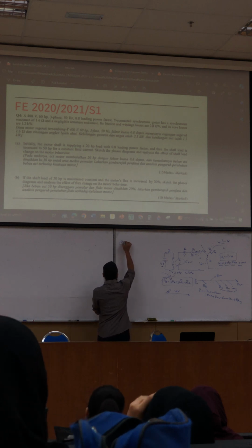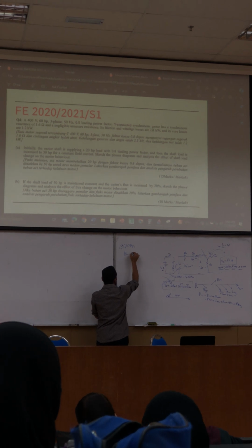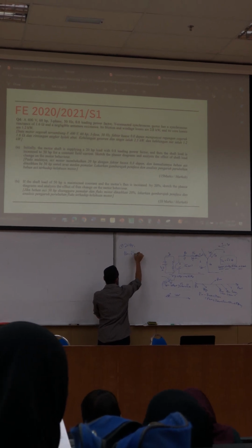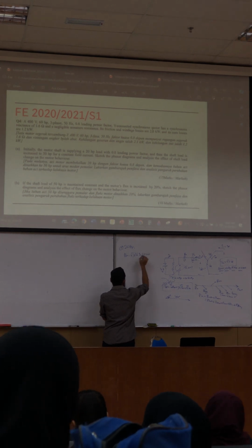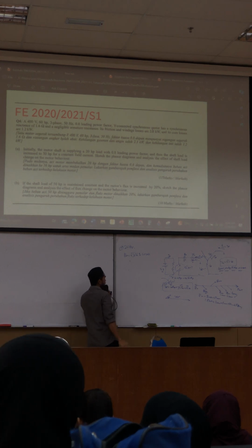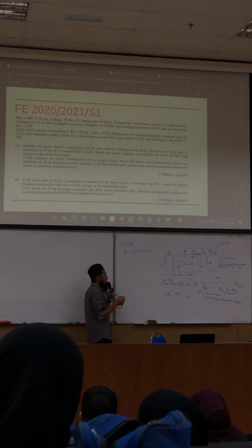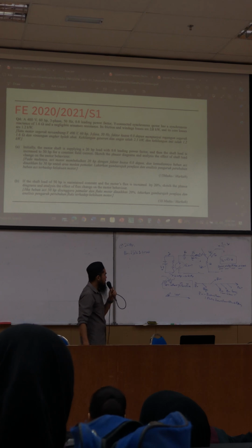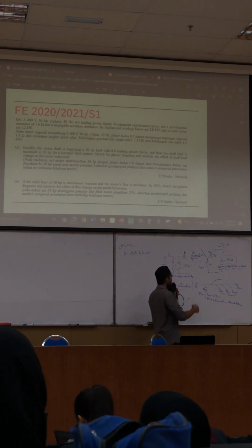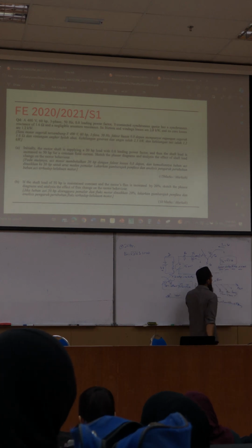So at 20 horsepower, P in is equal to root 3 V line I line cos theta. Line here is your line current or voltage in RMS value. If let's say you are given in peak, so change to RMS first. But now, since this one is already in RMS, so you just use directly.